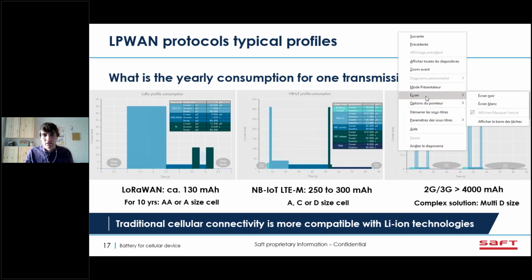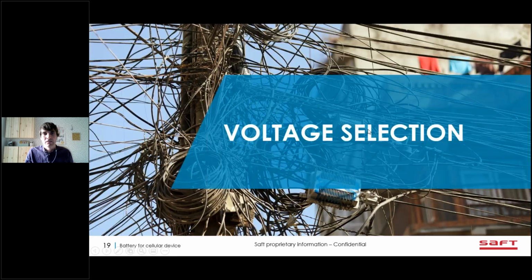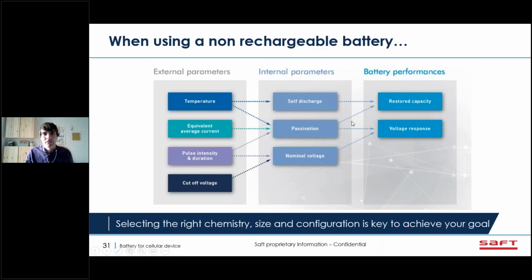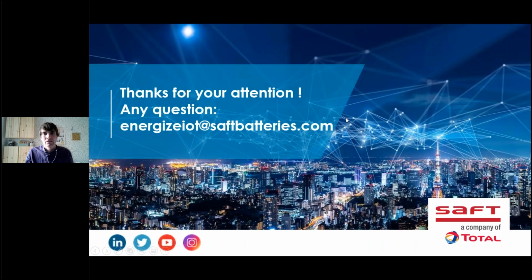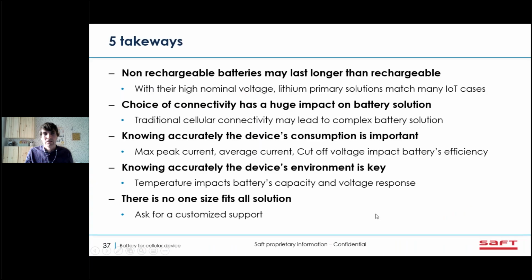This is exactly what is said at the end of the presentation. There is no one size fits all, clearly. For some applications, lithium thionyl chloride will be the most adequate solution. For some others, it will be lithium manganese dioxide. For some others, it will be lithium thionyl chloride, but with a pulse helper, a hybrid cap or supercap or something like this.